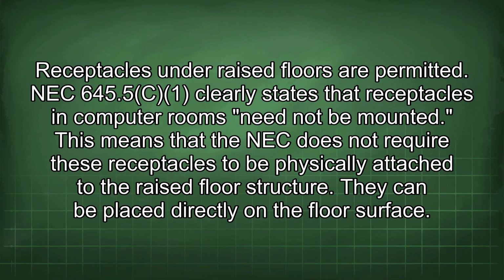Receptacles under raised floors are permitted. NEC 645.5 clearly states that receptacles in computer rooms need not be mounted. This means that the NEC does not require these receptacles to be physically attached to the raised floor structure. They can be placed directly on the floor surface.